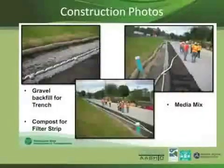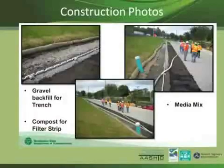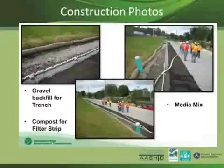From what we learned from this one, we want to limit the flow spreader to a maximum of 50 feet or so, so that it's easier to control. This is the final product here. After we built it, we brought a water truck out there, and you can see on the right picture that some of the water is concentrated in one location and not spread out over the entire length. But eventually we fixed it, so it works now. Next slide, please.